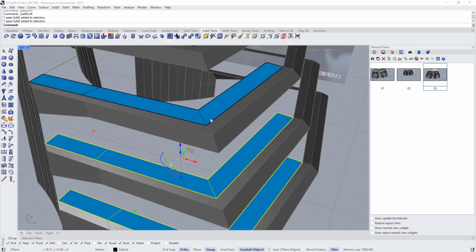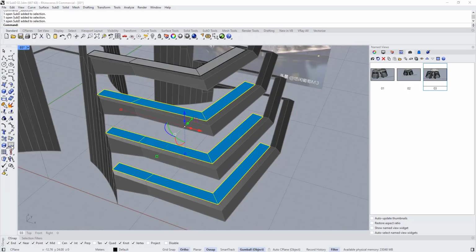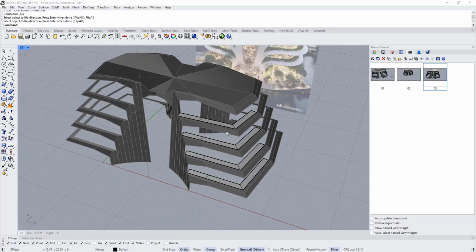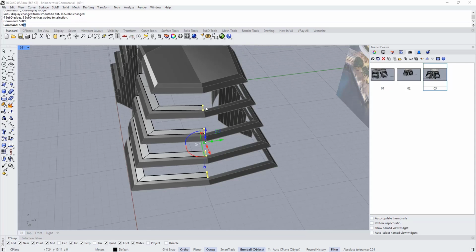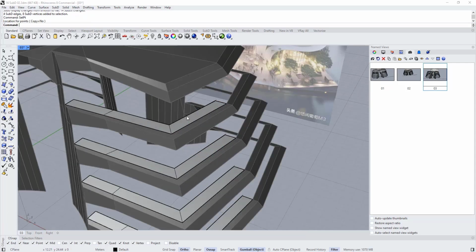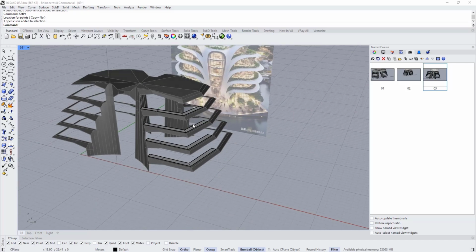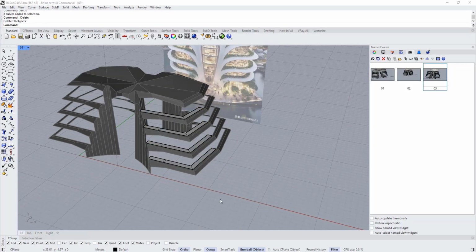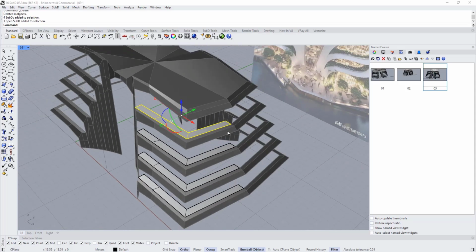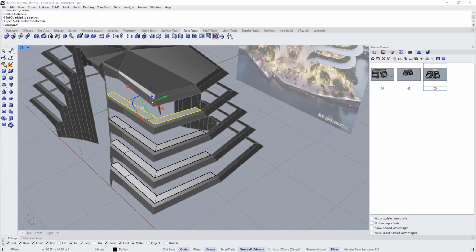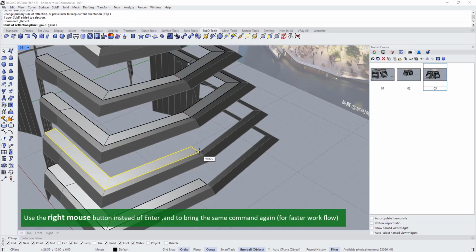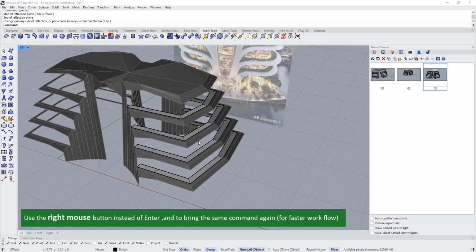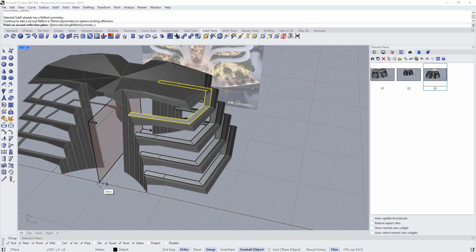So okay, for this SubD, I just need to flip the normals to match the other. So I'm going to hold Control Shift and select all these edges and type set point, set it in this direction, which is the Y direction, and align them like this. Now we can type SEL curve and delete all these curves. I'm going to also use the reflect command on all of these SubD faces, and I'm going to create a reflect here also.